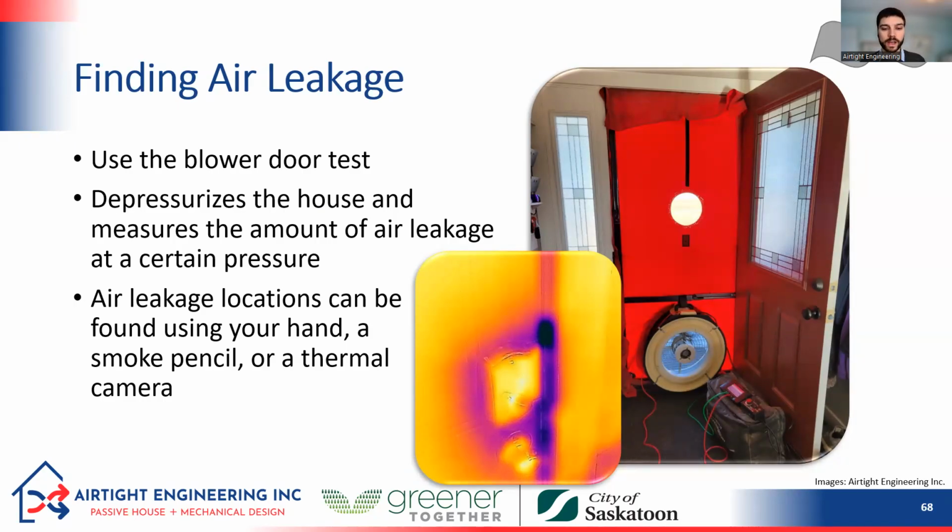So here's a picture of that here. Here's a door lock set, and you can see a big air leak right here just above that door lock set, kind of above the deadbolt. So it's showing up black because there's cold air that's rushing in through that gap because we are putting on the blower door fan. So this blower door is kind of simulating a big windstorm hitting all sides of the building at the same time, the air leakage that we might expect from that.